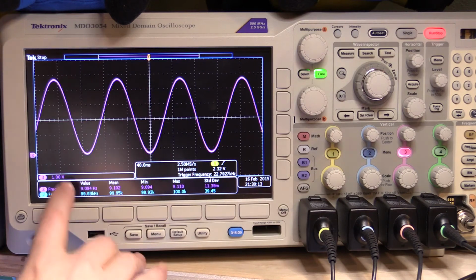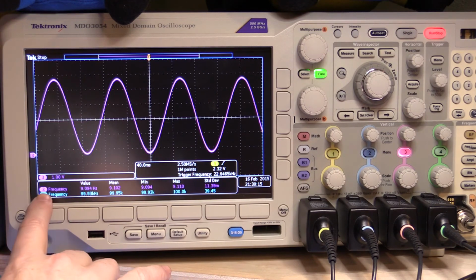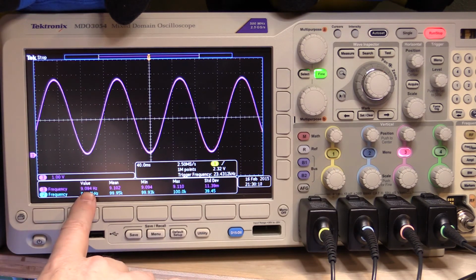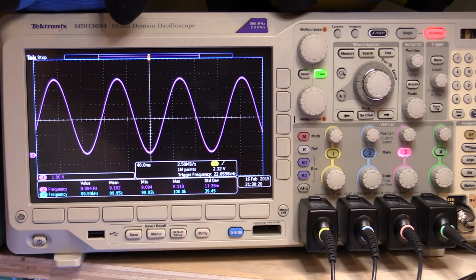I've actually got this measuring the frequency of channel 3 and 2. Its frequency is only 9 Hertz, so that's a fairly tight loop using Wiring, reading the 16-bit values. So whilst it is producing a nice sine wave from that table, looping it through 255 times and doing the 16-bit values as flat out as it can, it's only managing 9 Hertz.